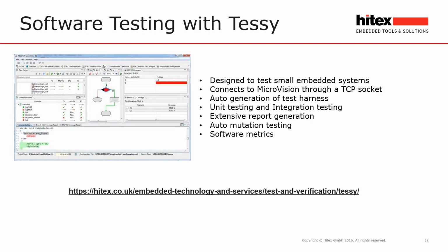Now, if you have a lot of testing to do, with the Unity framework you quite quickly hit its limits. Every time you make a change to a function, you have to maintain all of your test code. You then have to spend a lot of time doing all the documentation as well. So it's good as a test framework to build confidence, but if you have a large amount of testing for a safety certified product, you will start to hit the limits of what it can do.